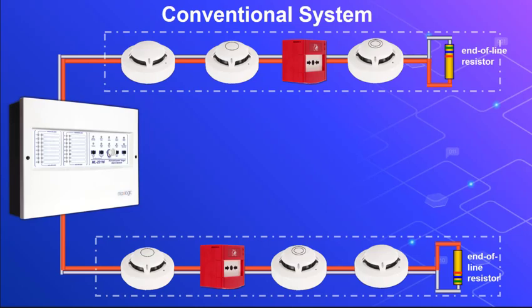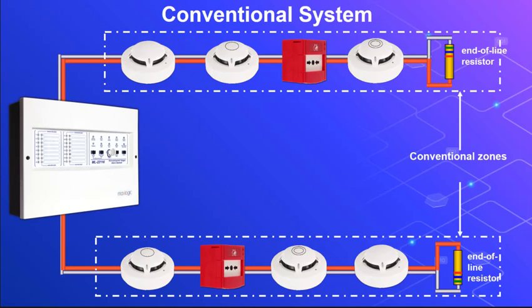Fire detection and warning systems working with the regional notification method are also called conventional systems in the market and written sources. The working principle of these systems: they work by connecting multiple sensors and manual warning devices sequentially on the same cable line and monitoring the end of the line as an electrical circuit, with the principle that any of the detectors or buttons completes the circuit over the alarm register, and the regional notification is displayed in the control panel. The notification from which sensor can only be detected by going to the area.